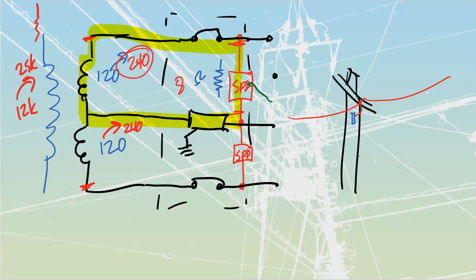That tubular device is then going to have a ground conductor that runs all the way down. We'll stick it behind a guard so it doesn't get ripped off or anything like that. But what that is, is a stack of thyrite discs inside of that tube. It is constantly connected to ground. There are milliamps of current traveling through it. There has to always be milliamps traveling through it. You will see that these are well protected as well because they do provide a continuous path.